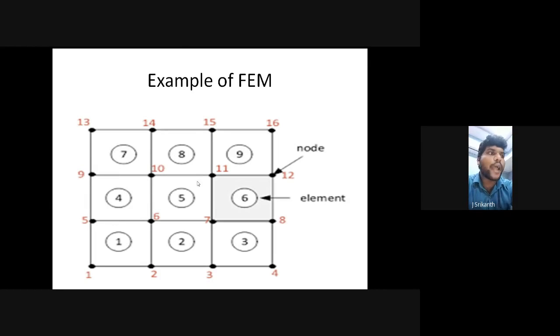With the help of the finite element method, we choose only one brick to find the stresses, the displacements, and the strains also. The strains in brick number 1 are equal to those in bricks 2, 3, 4, 5, 6, 7, 8, 9. So we find only one brick, and the same values will be taken for the remaining bricks.